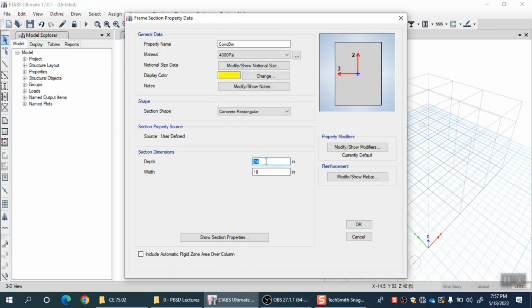So you have to make sure that whenever cross section size is changed, you have a new cross section definition. Whenever a material is changed, you have a new cross section definition. And now another criterion, whenever the amount of steel is changed, but the other two are still the same, you again have to define a new cross section, right?